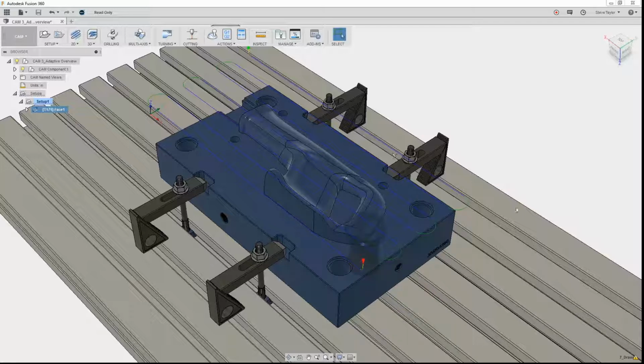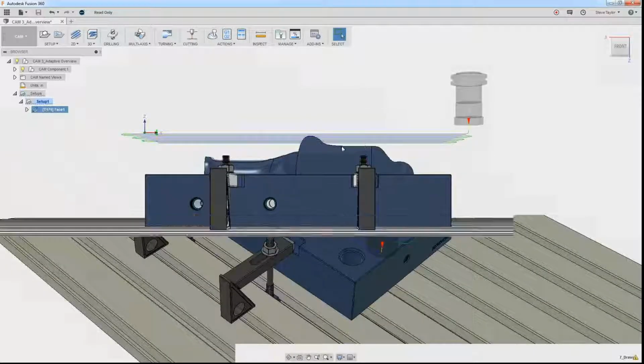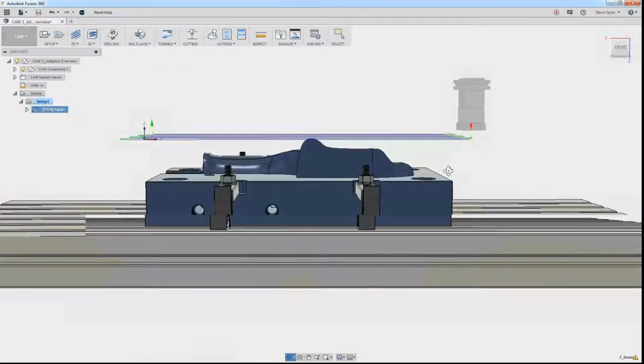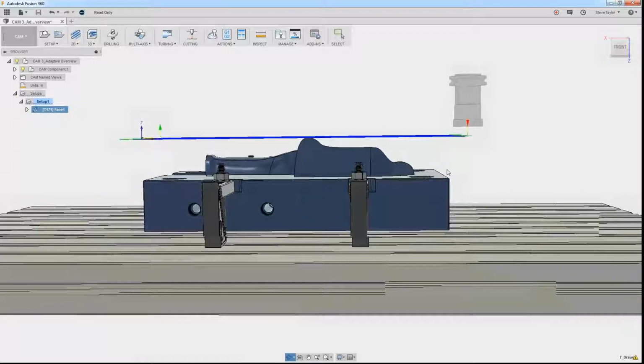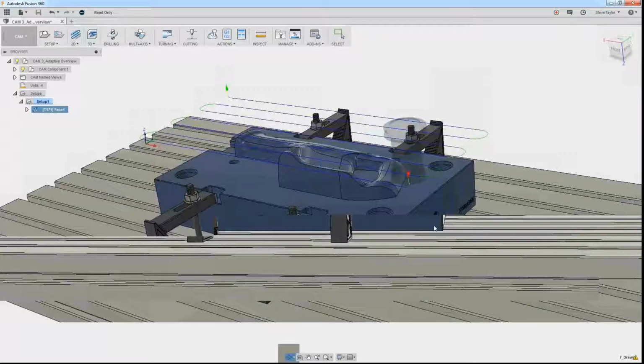We've got this solid block. If I view this around to the side, you'll see that tool path is above where we are. We've got a stock box that goes across, and all we're doing with this tool is facing it flat on top, so that we know we're all at a certain height all the way across.